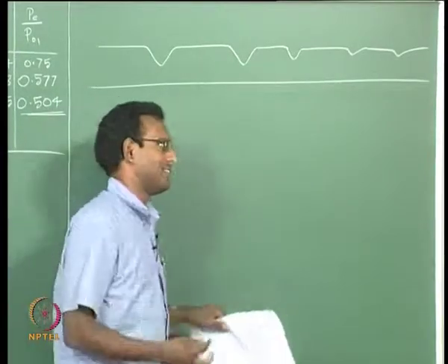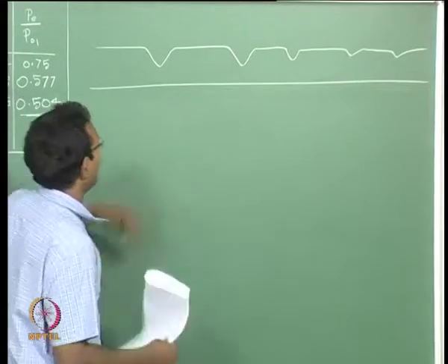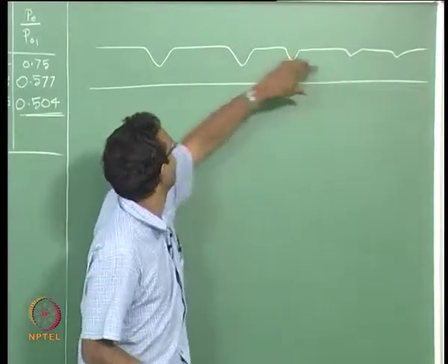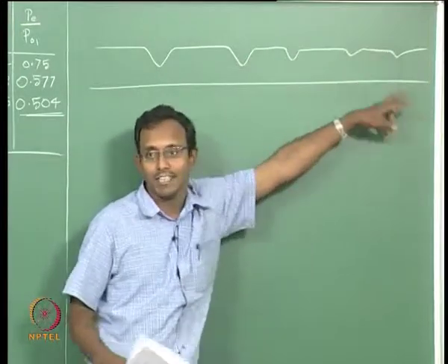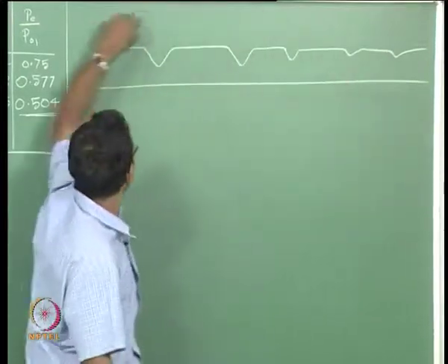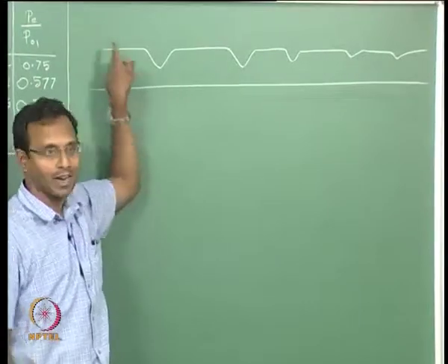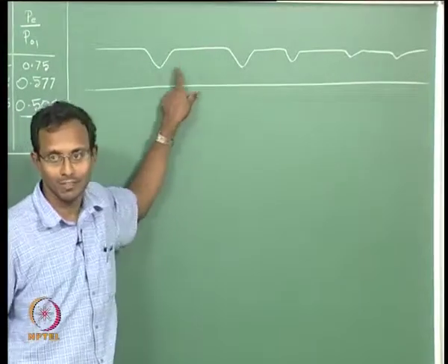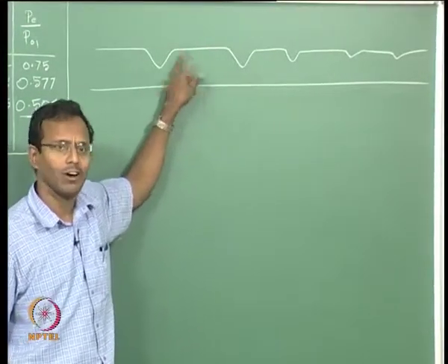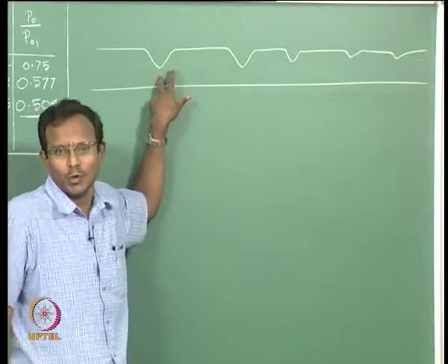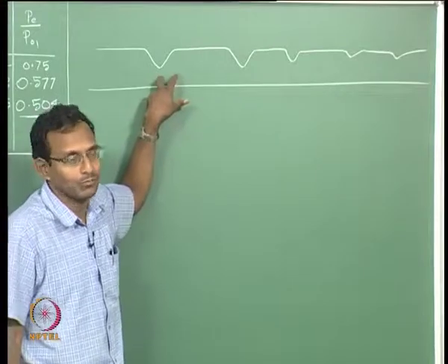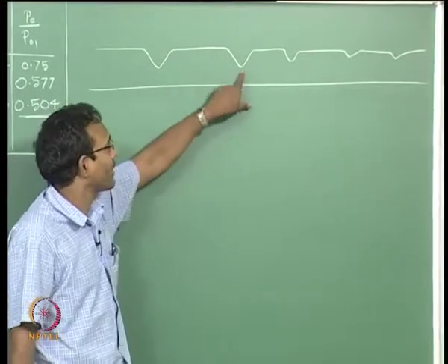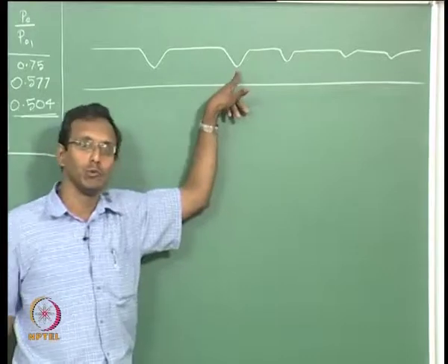Okay. Let us say initially I did not have any of these bumps, I just had one CD nozzle and then a straight line duct. I set some pressure P naught and I know it became supersonic after this point. Or if you want, I just worry about choking, it choked definitely. I went below P critical 1 for this throat, it choked. After that, if I wanted to choke again, what should I do?